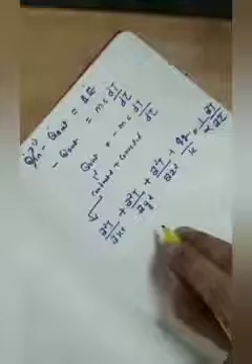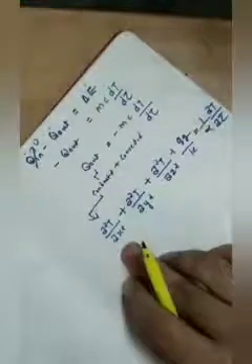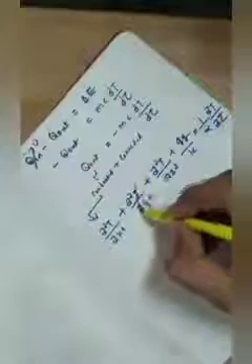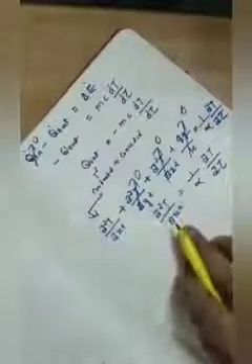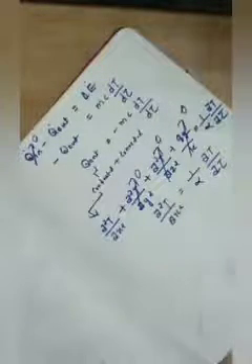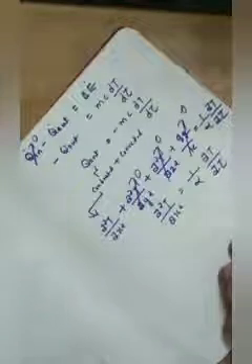In this slab the heat is transferred in one dimension, so all other directions we can assume as 0, and there is no heat generation within the system, so this is also equal to 0. So the conduction equation becomes ∂²T/∂x² is equal to 1/α ∂T/∂τ. To solve this equation, which is second order in x, we require two boundary conditions here and one here. In total we require three boundary conditions.